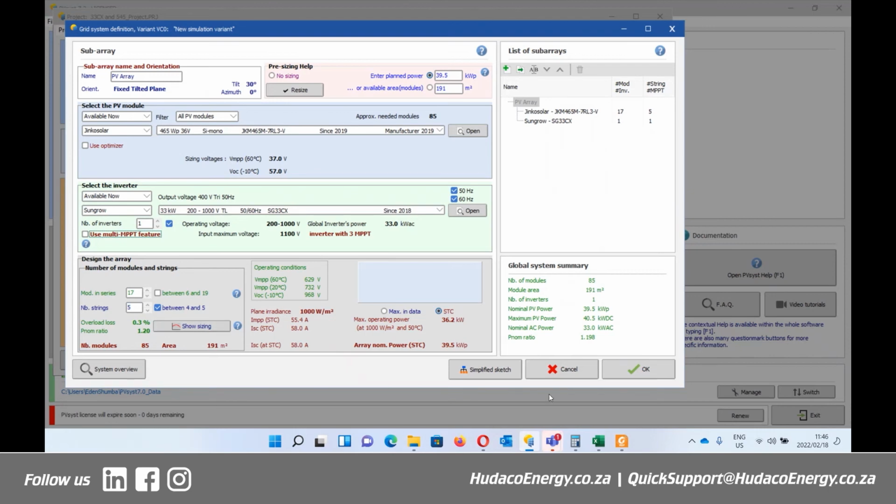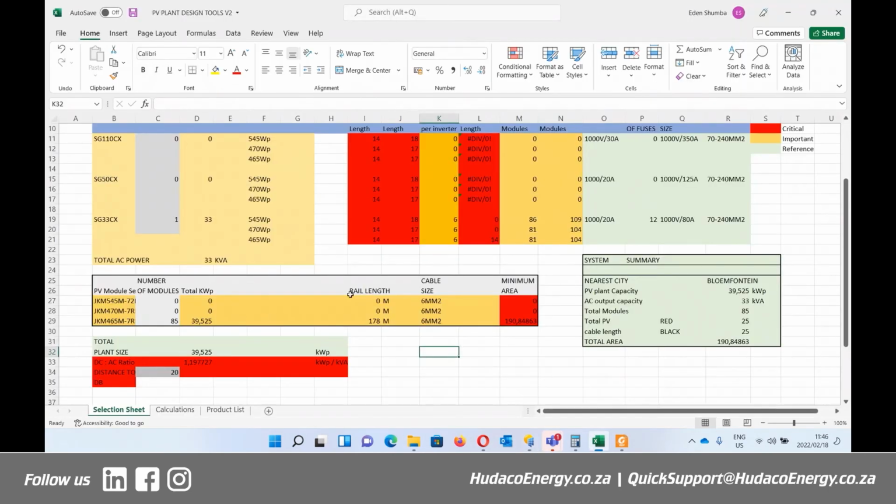But with us, we have chosen to use all the 6 inputs. That is why our string lengths are not going to be 17 per input. They're going to be 14 because we are using all the 6 inputs. That is the difference between our design and their design.